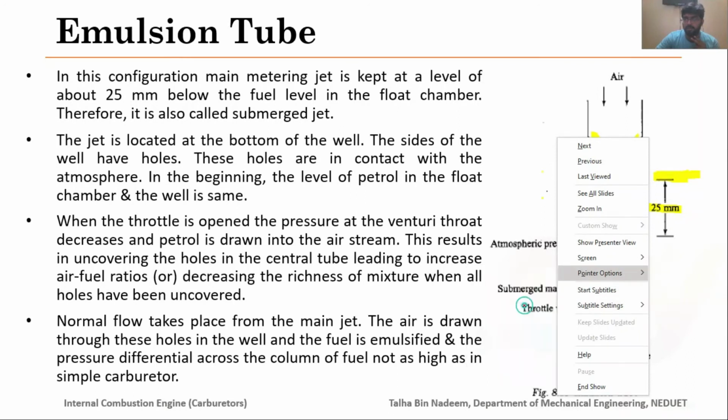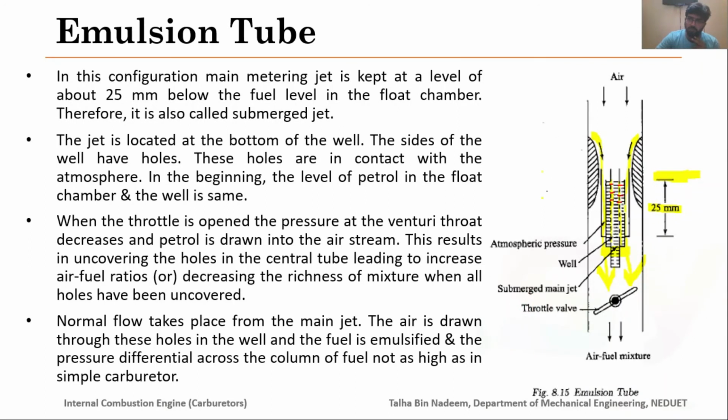As the fuel is being taken away by the incoming air, the fuel level will start dropping, and as the fuel level drops, these holes will ultimately be uncovered.